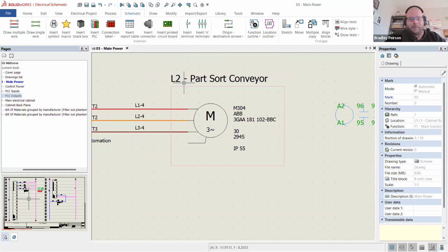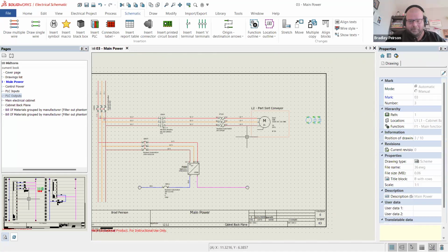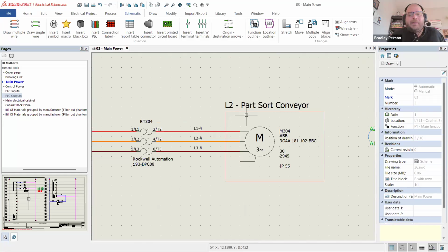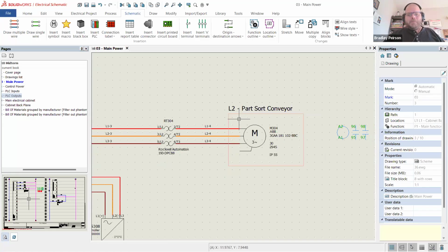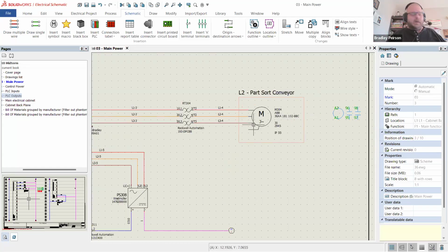But it tells me this thing now, I mean, it's pretty clear this is in a different location. This motor is not in the back cabinet, right? The whole drawing is the motor is not. So that is a powerful use of locations. I highly recommend, beyond just the fact that we needed locations to sort of cheat and get more 2D drawings, using locations for things like this, especially in complex and big equipment.